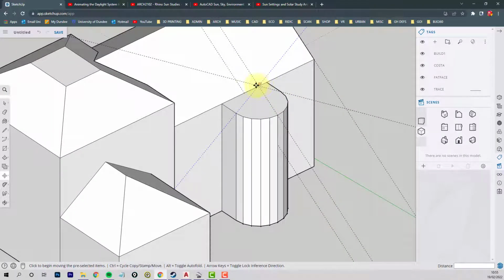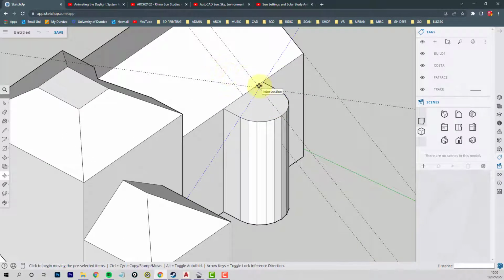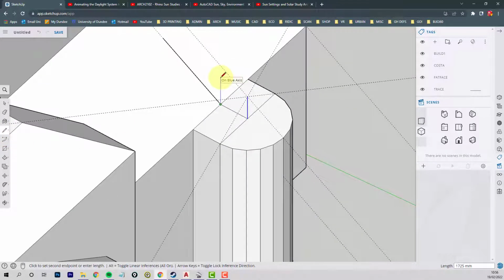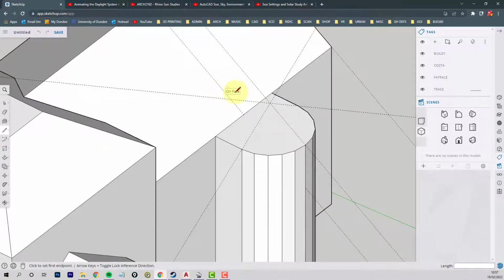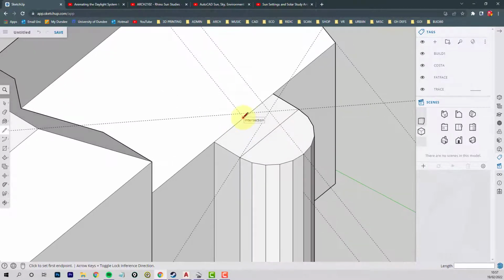Okay, so we've got the position for our radial bit of roof, and we need to try and get a line back from here. Let's create a bit of temporary geometry here, see if we can get this collision position here. So I'm going to draw across here, draw up the roof line there, draw downwards here, draw across, and draw back up, and that's now lining up with the first point.